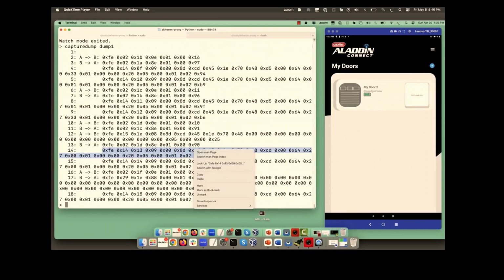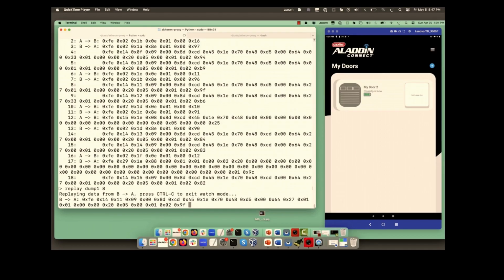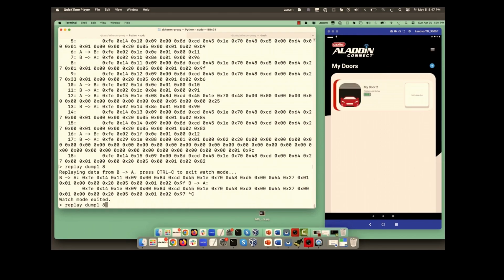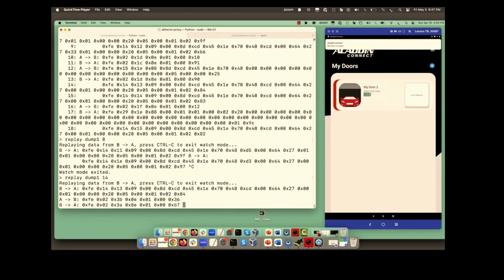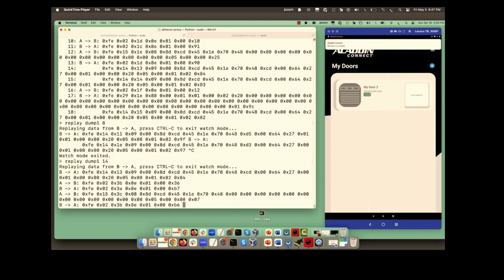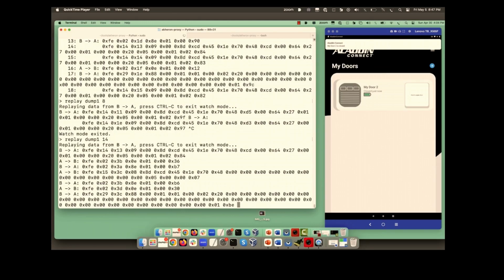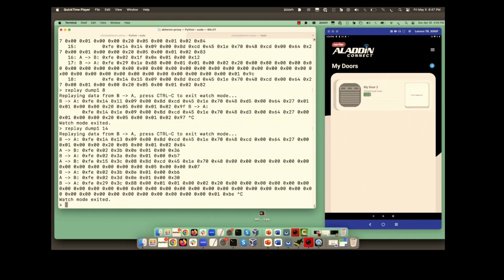Now I forced the lock to close. Now I'm going to send an interchip command here, and it's going to actually open the device. And this data is actually going to the cloud. If we think about this, inside here is some kind of communication that identifies this particular device to the cloud. If you could get the control key that's associated with someone else's device, because they were on YouTube, you could potentially start telling their cloud services, hey, here's this device, it's open. Just keep sending it open. The poor guy thinks it's closed, now it's open, because you can lie to him.